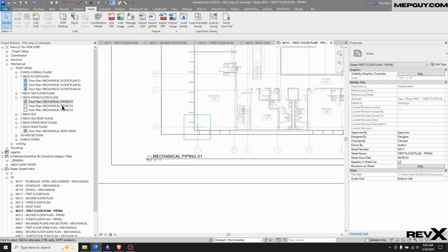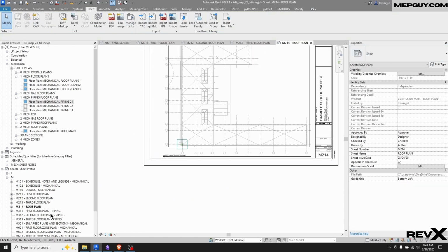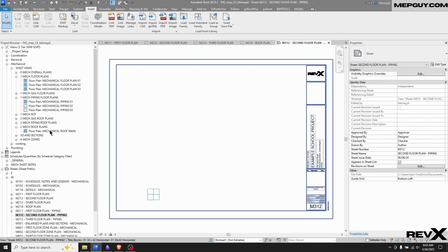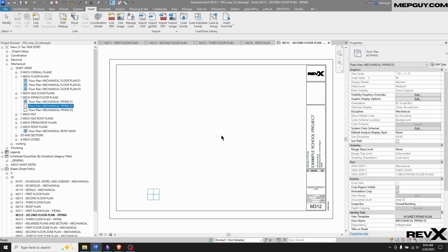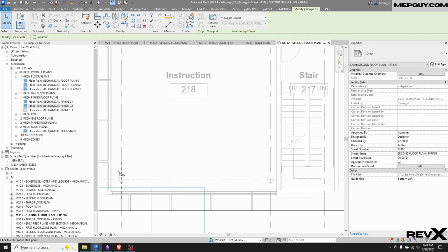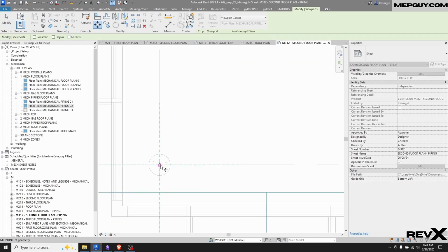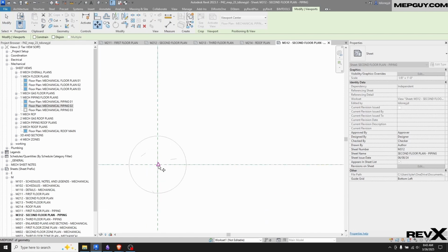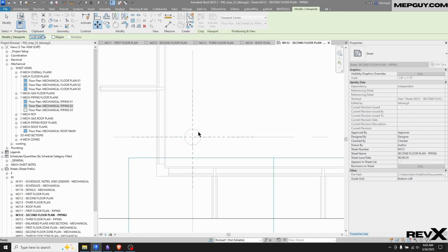So I've noticed what's happening here, why I'm getting, oh, well here, let me show you, piping, let's say learning moment. What's happening when I enter the move command, I'm getting that triangle. Triangle means it's near the midpoint of a line, but that's not exactly where the crosshairs is. So it's causing me to spend more time to get that crosshairs, which is wasting time in my model setup, so I want to be more efficient with that.